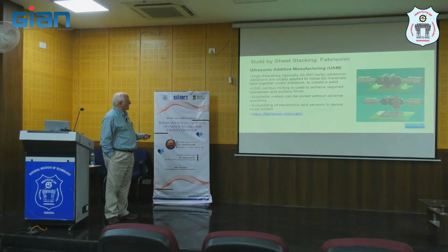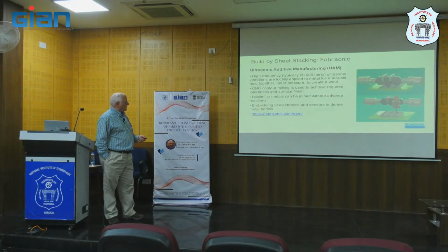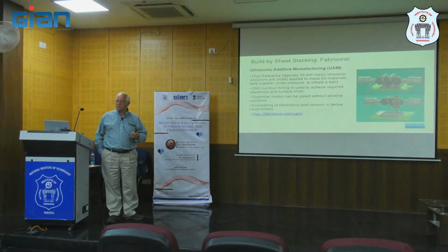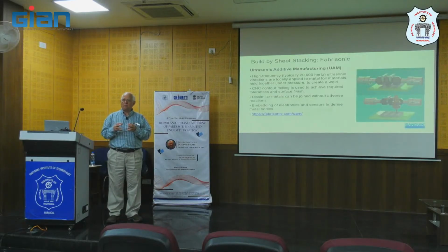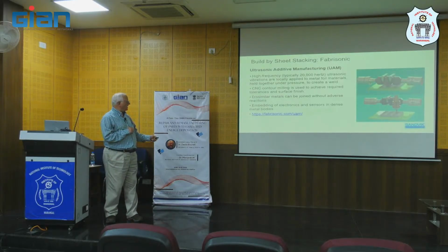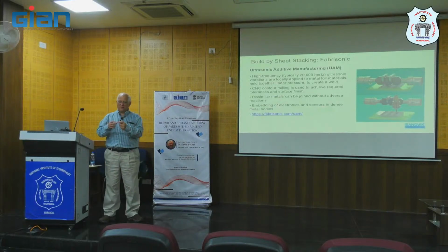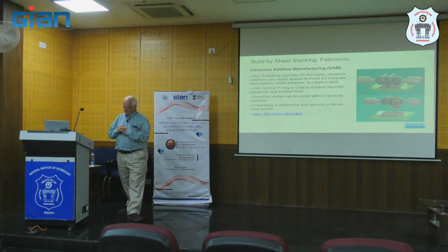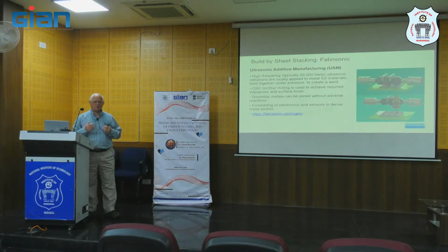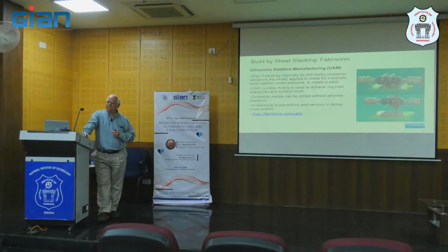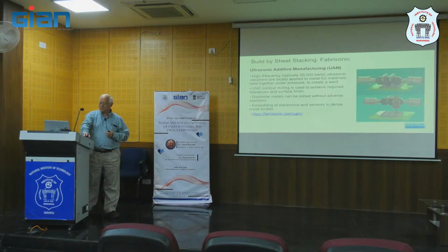And then, as I think I may have mentioned earlier this week, because it's a room temperature process, it's a way to produce a metal part that has thermally sensitive equipment like electronics or sensors. Basically the way this works is they build a cavity for the sensor, then place the sensor and just keep building. So it's possible to do that. It's the only additive process I think that's really amenable to this kind of approach.